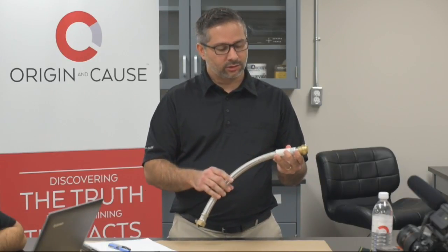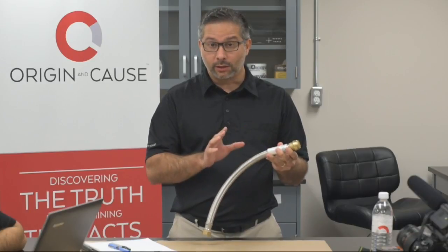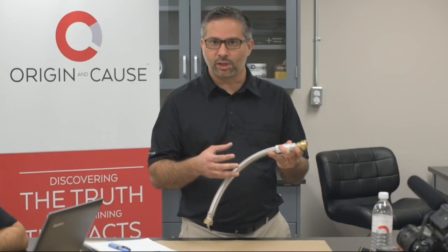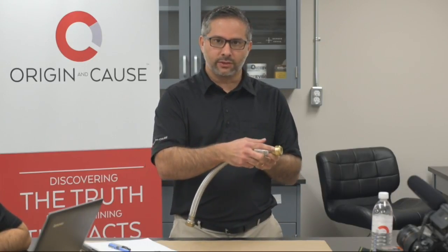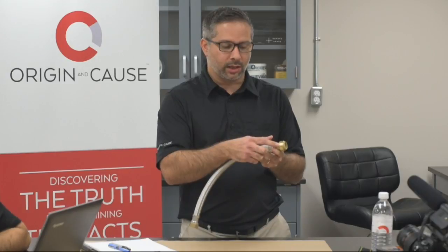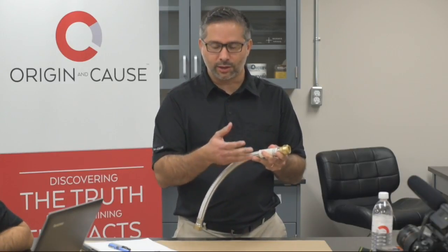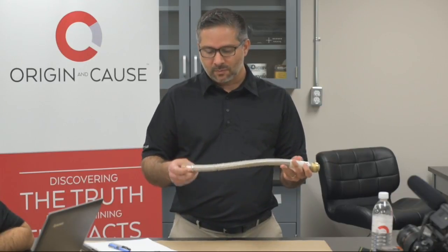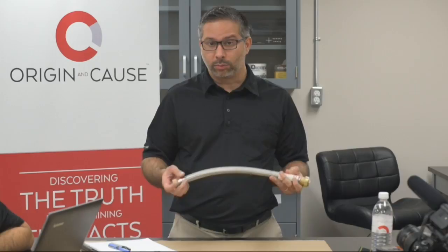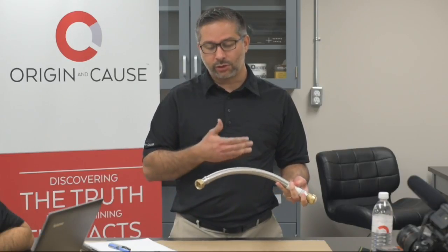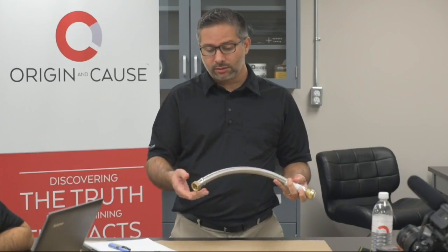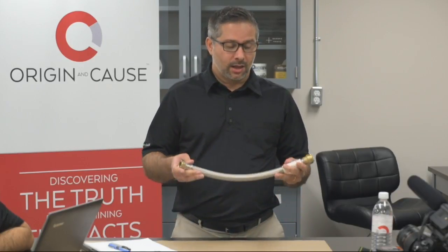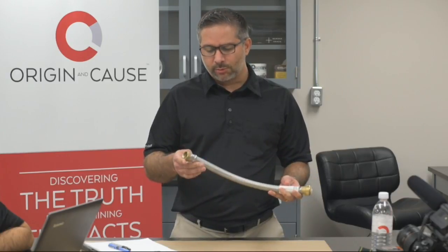Lots of them have a tag, but they're all required to have markings that cannot be removed. So in this case, they have engraved markings naming the model or the manufacturer name. You can find them on the fittings. You can find them on the crimps. Sometimes they're very small, very blurry to see, and sometimes we have to use a microscope to find them. But they are required to have it, and normally we can find them without much trouble.